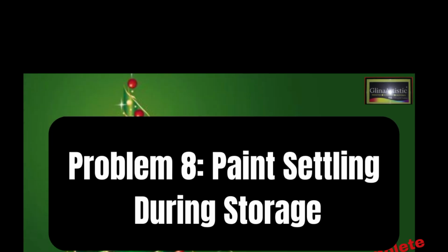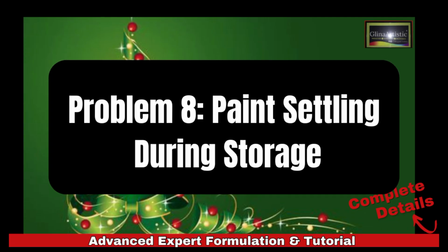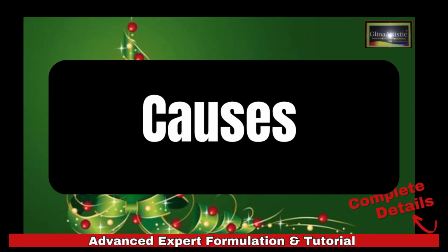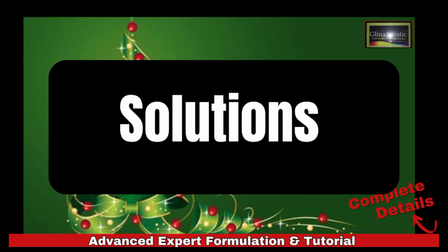So now problem number 8: paint settling during storage. The symptoms are pigment settling at the bottom of the container. Causes are lack of anti-settling agent or low viscosity. And how can you solve this? Add your xanthan gum or bentonite clay as anti-settling agent. Regularly stir your stored paint over time.